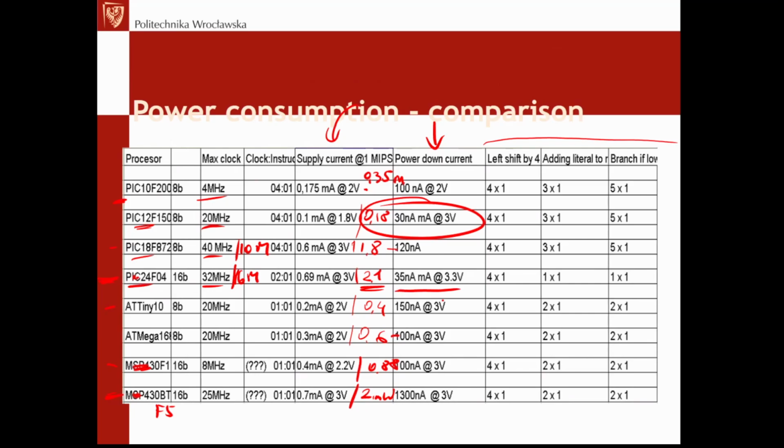which means that statically it's designed perfectly. I would even say superbly with just 100 nanowatts, outpacing the ATmega, for example. So PIC24 is giving you higher processing power, 16-bit operations, and of course actively it requires more than ATmega, but in the sleep, in power down mode, it's even better.